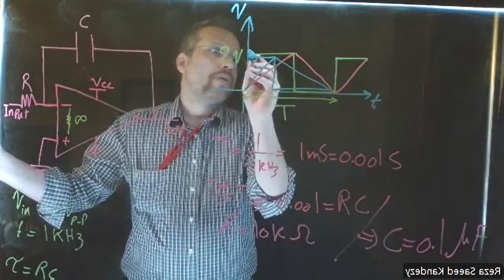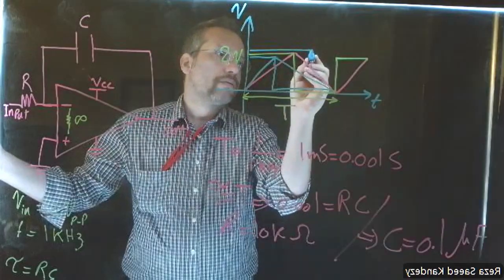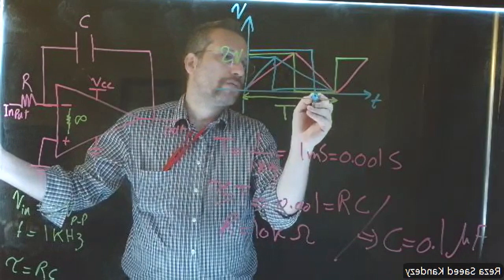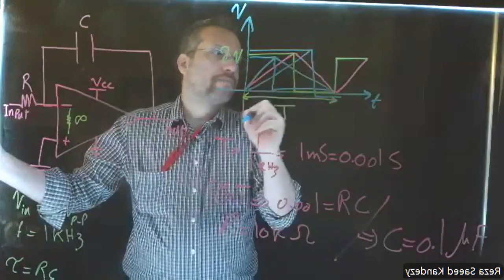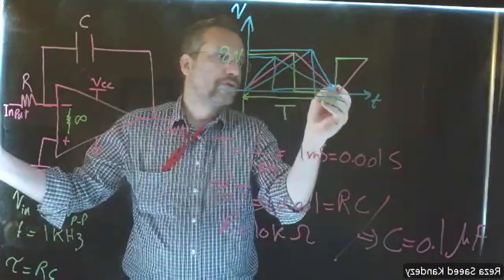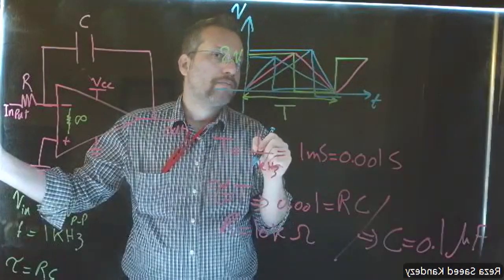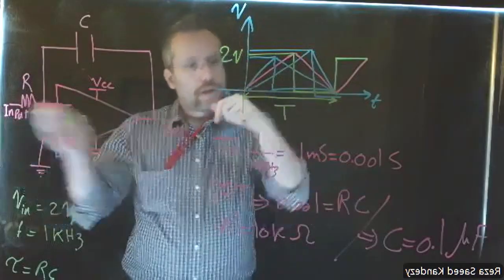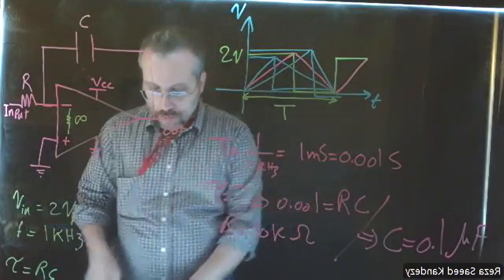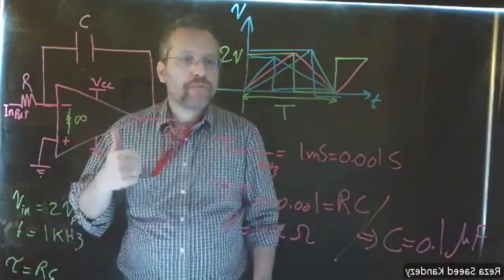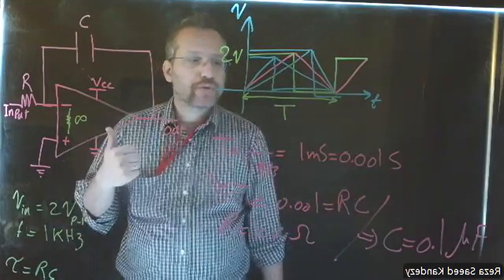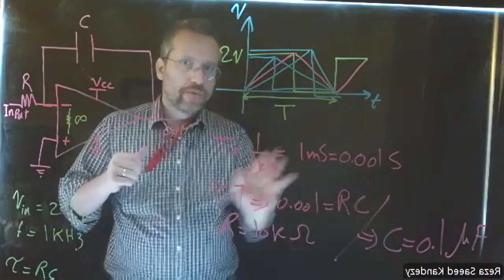And if I go higher in the duty ratio, that means I have a lower slope of rise time and higher slope of fall time. Are we good? Now let's go to the lab to see if what we have in the lab actually meets our theory and our design.